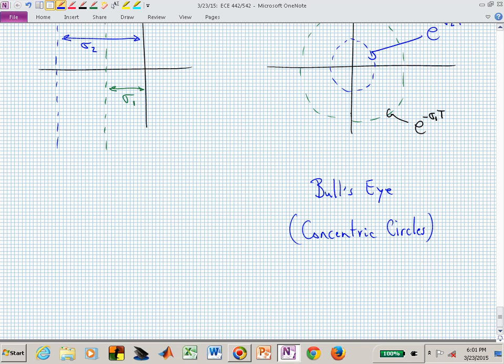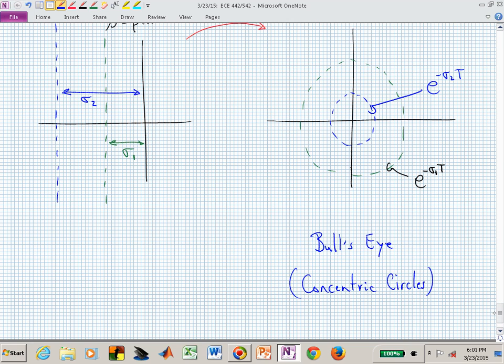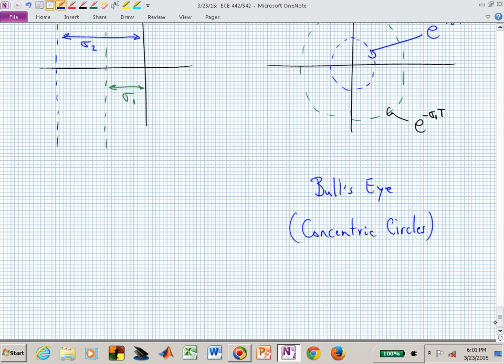And the smaller your circles are, the faster your system responds. If you want to speed up your system, shorten your settling time, make your system settle more quickly, which of these circles would you be targeting? Your green circle or your blue circle? The blue. You want to be closer to the origin in the z-plane. That radial distance impacts speed.